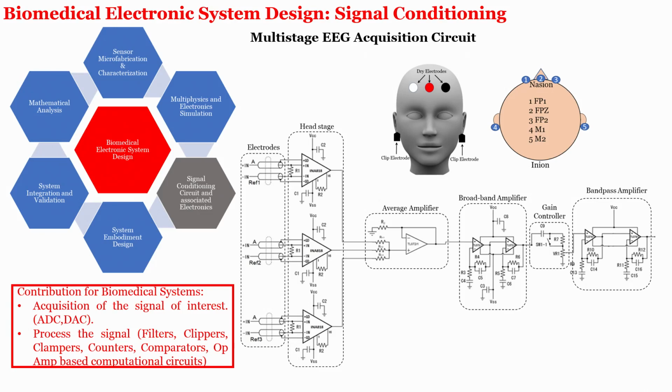So, we went into details about the electronic system, but when we talk about the electronic system, we also have to talk about the electronic module, particularly for EEG signals, since EEG signals fall in microvolts compared to millivolts of ECG. If you measure ECG, it is about millivolts. If you measure EMG, about millivolts. ECG is electrocardiography and it is from the heart. EMG is from the muscle, electromyogram. EEG is electroencephalogram, that is the brain signals.